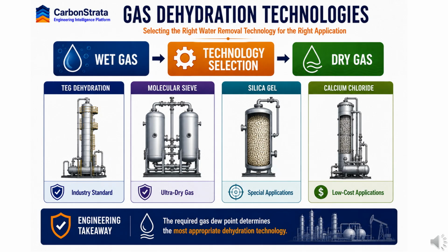The best practice framework shown here follows 6 key steps. First, assess and plan by evaluating risks and selecting the right strategy. Next, prevent hydrate formation using methods such as dehydration, inhibitor injection, or operating controls. Then monitor critical parameters and respond quickly to any deviations before they become operational issues. The process continues with verification of results and ongoing improvement through performance analysis and optimization. This creates a cycle of continuous improvement rather than a one-time solution.